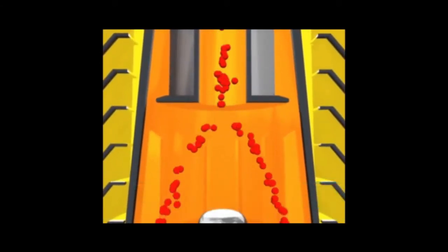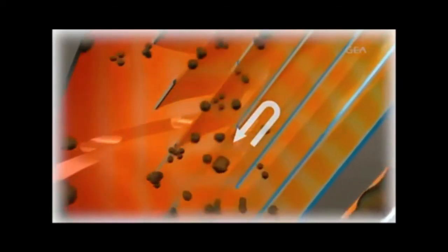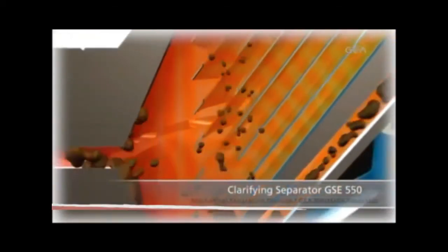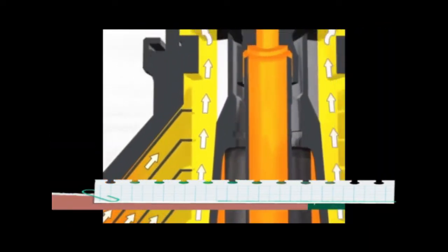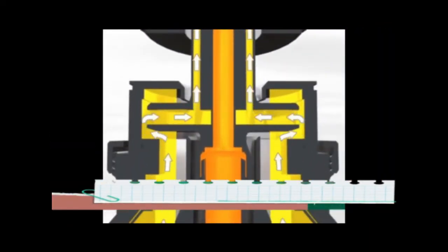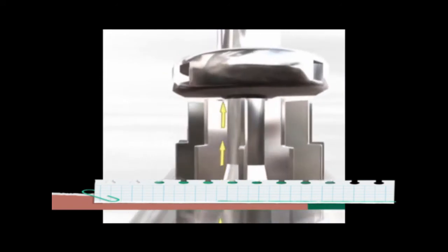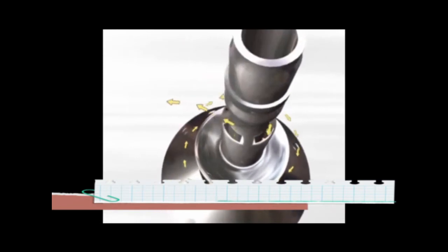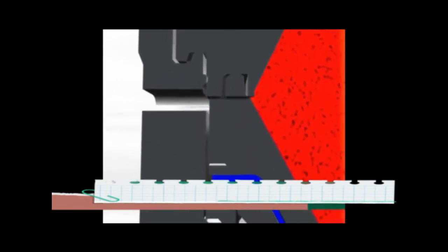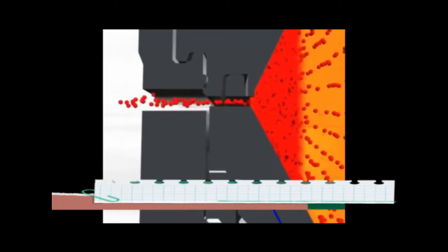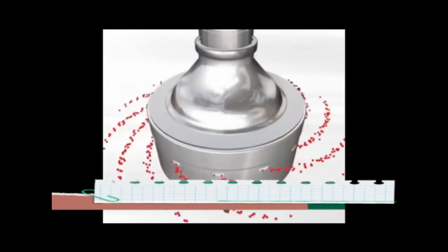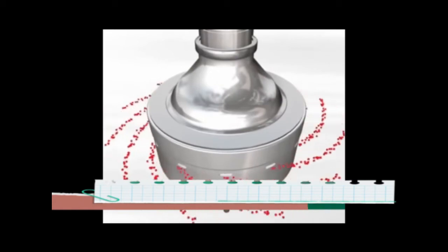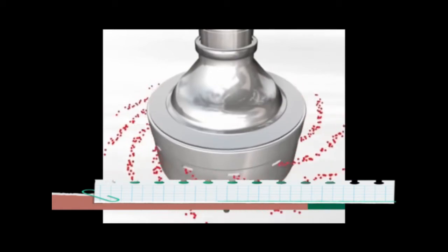No interface is formed, the bowl therefore operates at maximum separating efficiency, since the oil is subjected to the maximum centrifugal force. The untreated oil is introduced to the rotating centrifuge bowl from the top, and is accelerated in a distributor before entering the disc stack. It is between the discs that the separation of the solid impurities takes place. The cleaned oil phase moves upward, and is discharged by a pairing disc, or a centripetal pump, from the bowl to the service tank. The heavier solids phase is collected at the bowl periphery, and either discharged out by manual or self-cleaning clarifier, to the sludge tank.